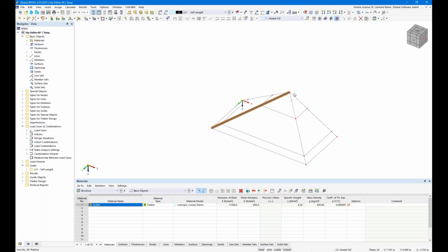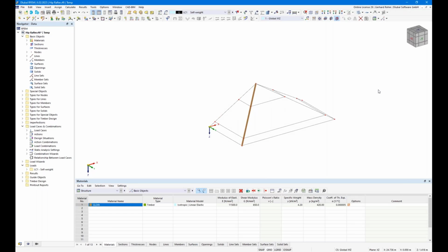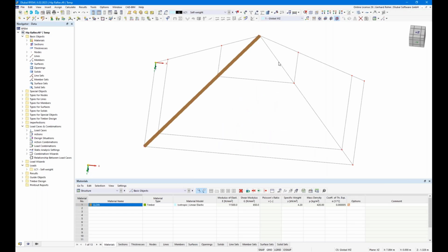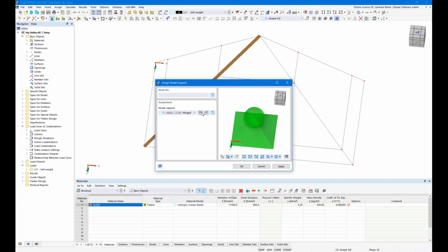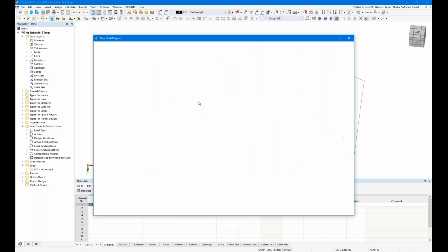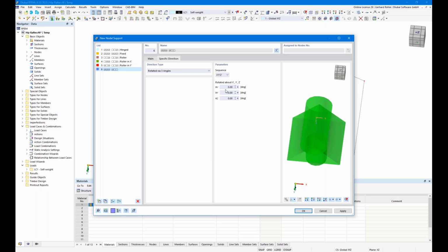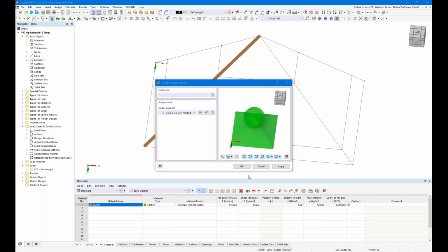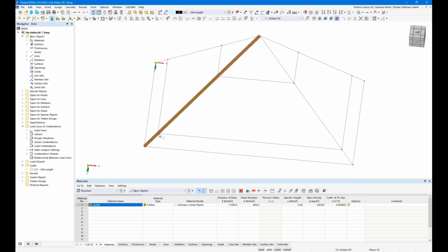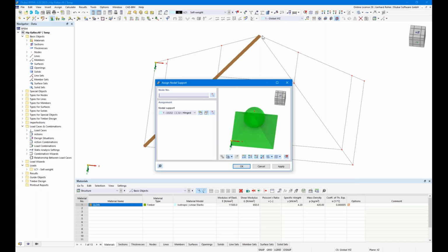I don't want to have the beam also here because it's the same, it's symmetric. So I just added this to the structure to show you what is possible with the loads and so on for later. Okay, then of course we have the beam, we need support. So I create just 2 nodal supports. Of course, I need to rotate the supports by -45 degrees in this example. So I fix support on the bottom and the sliding support here on the top side.